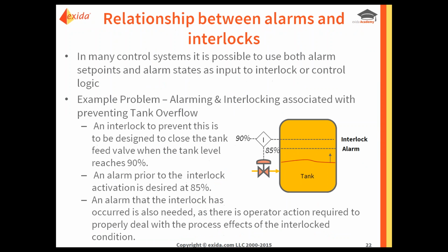So one of the things we want to talk about then is that in many control systems, it is possible to use the alarm set point and/or the alarm state, meaning whether it's active or not, as input to interlock logic.